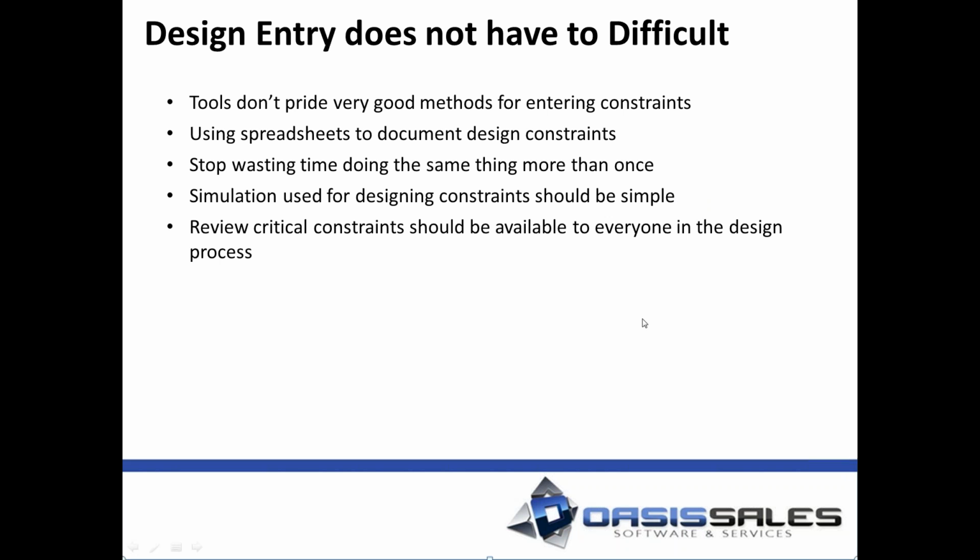And for those of us doing simulation type design rules, where it requires a signal integrity tool or even analog simulation to define those constraints, why should you have to go to a second tool, define the constraint, and then import that information and recapture the content that you want to simulate, when your schematic tool should have the ability nowadays to take the information right from your schematic and pull it into a simulation application so that you can run your scenarios and then create those constraints needed for the PCB design.